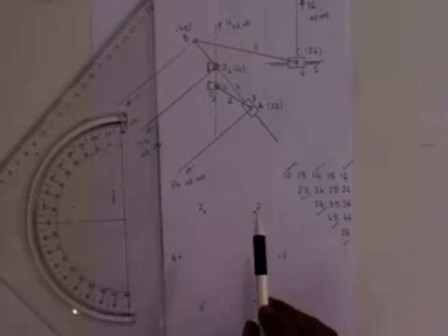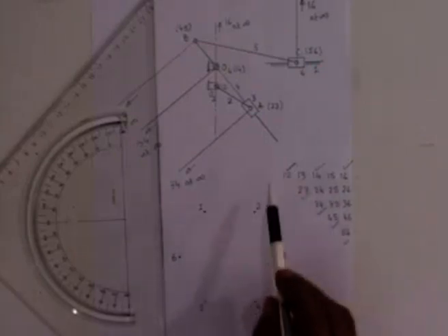So, I have located 1 6. So, because of the 7 kinematic pairs, we have just by inspection located 7 out of these 15 relative instantaneous centers. The remaining 8 can be determined only by invoking the Aronhold-Kennedy theorem.